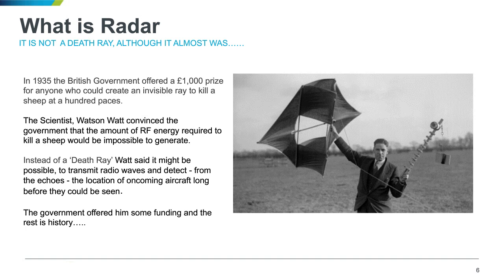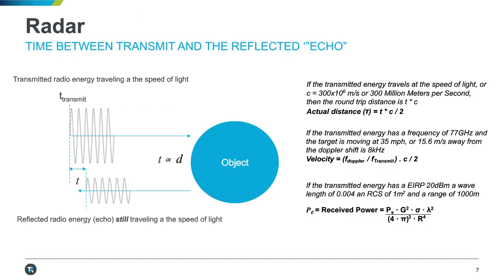So radar fundamentals. What are we going to do here? We're going to take a pulse of radio energy and emit it from an antenna. It will travel at the speed of light towards an object, and then it will reflect back off that object. The difference in time it takes that pulse of energy to bounce off the object and return is equivalent to the distance.